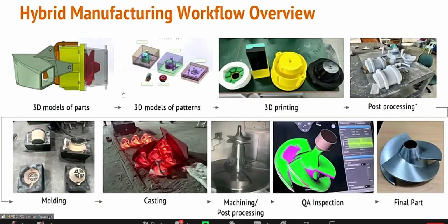So what we do is we spray, or we paint, we coat the 3D printed patterns with hard epoxy primer. So it's able to remove all those three problems all at once. It makes the pattern chemically resistant. It makes the pattern abrasion resistant. At the same time, we are able to sand it to a point where it's very smooth and pattern stripping from the mold is done easily.